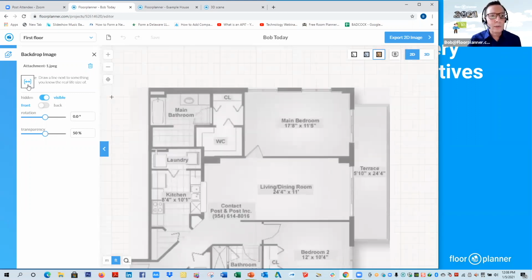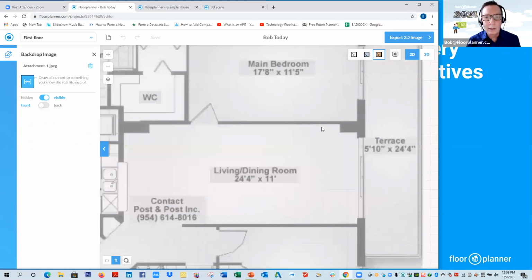and it resizes the background image. So you can do this multiple times too, because as the image gets longer, your crosshairs get smaller and tighter and more refined. So I can click this again, click that drywall again. You see that my crosshairs are a little bit tighter, a little bit more accurate, point to point. Type down here 11 feet, hit enter, tweaked it just a hair.